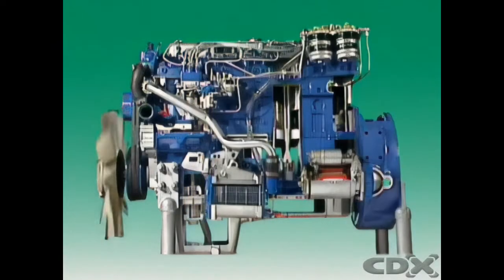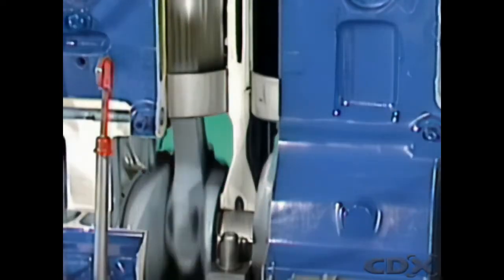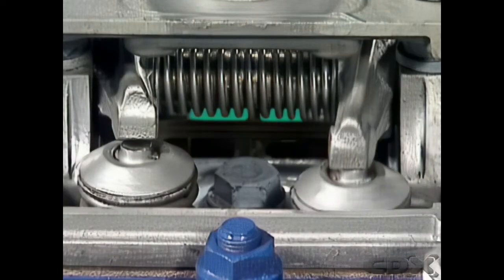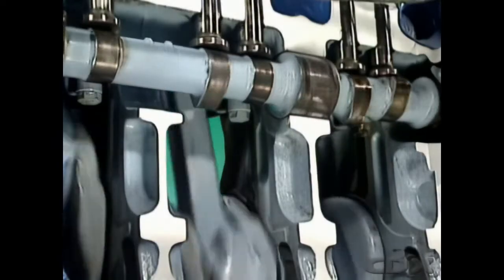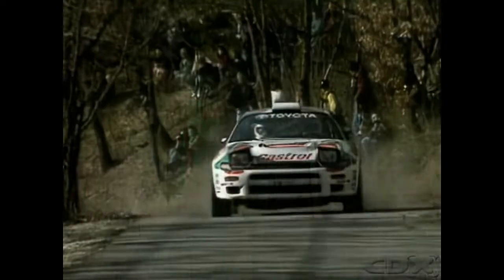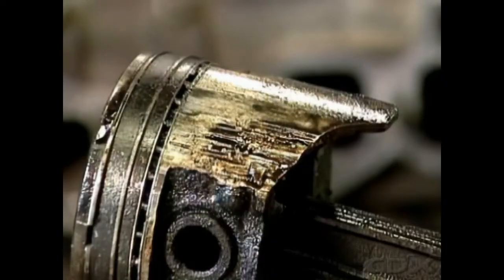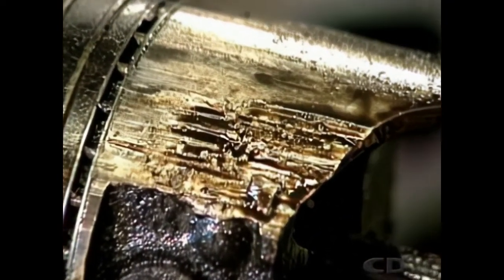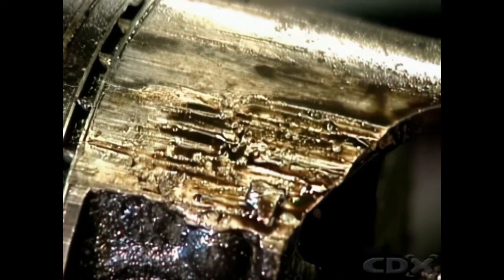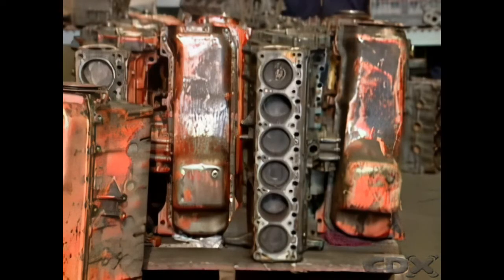One function of a lubrication system is to reduce friction. Friction occurs between all surfaces in contact. When moving surfaces come together, friction tends to slow them down. Sometimes that's just what's wanted. Friction can be useful. But it can also cause serious damage. It can make metal parts so hot they melt and fuse together. When that happens, an engine is said to have seized.